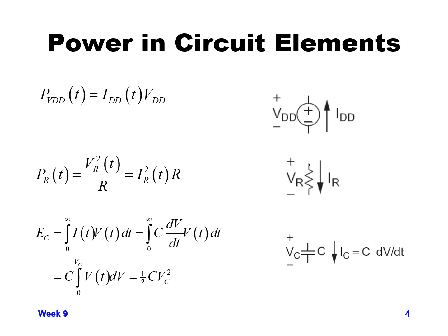And then finally, for a capacitor, we start out in terms of energy: the energy stored in a capacitor is the integral over time of the current going through the capacitor times the voltage across the capacitor as a function of time. Then we can substitute in the current through a capacitor, which is C times dV/dt. So we now have the integral of C dV/dt times V times dt.